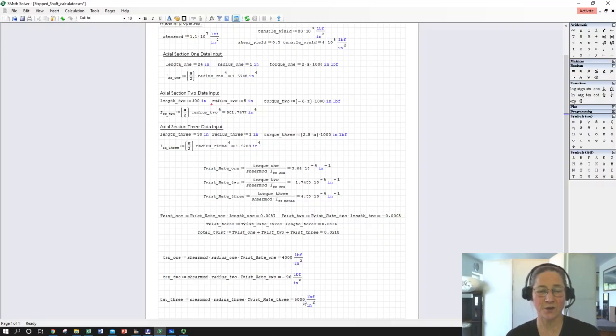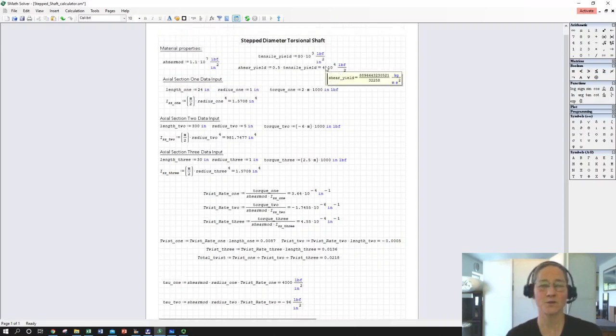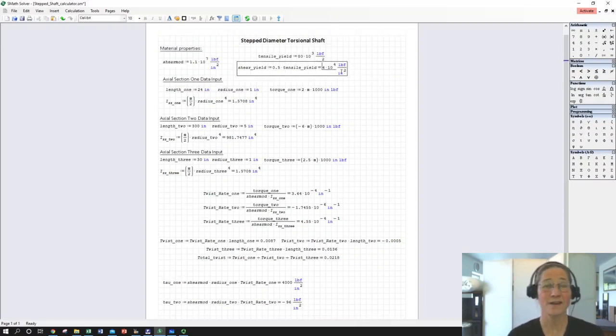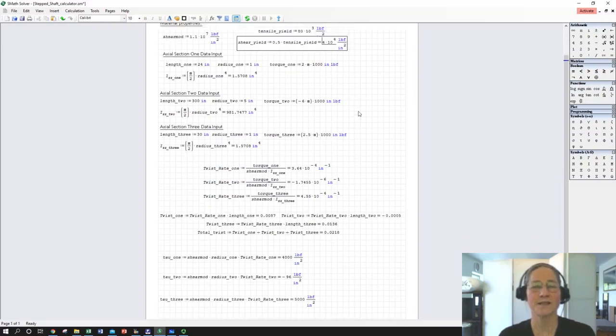If we're going to come down here first off and do a check on stress, right now we could say that we have more than or maybe a little bit less than an order of magnitude safety factor. So we have 5 times 10 to the third as our largest shear stress compared to 4 times 10 to the fourth shear yield. So we could go up 10 times in our shear stress before we would have to worry about yield. Now, generally speaking, you're always going to want to have a safety factor of, say, 2. So we could basically say we never want to go above maybe 2 times 10 to the fourth.